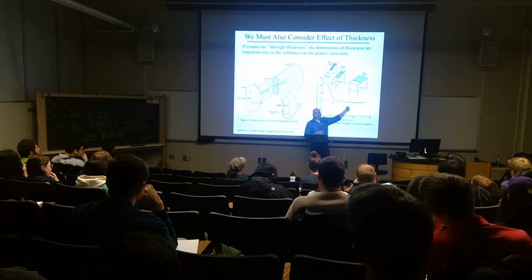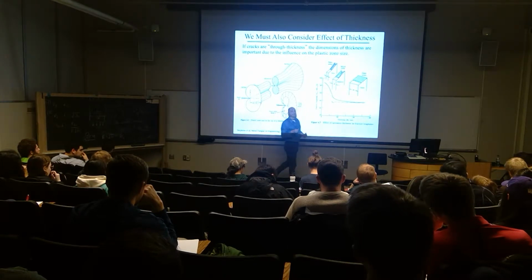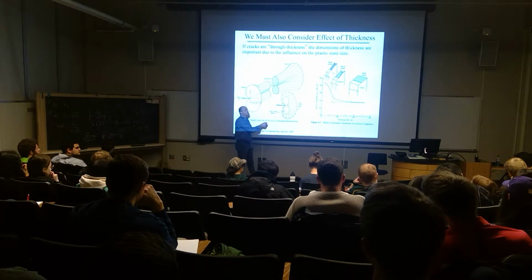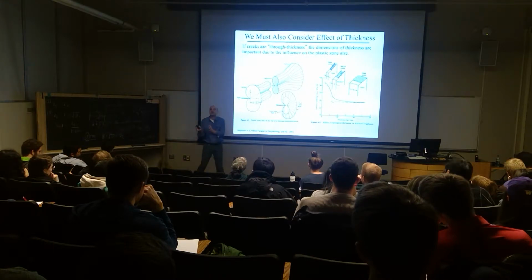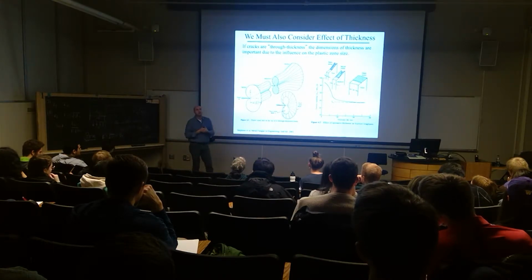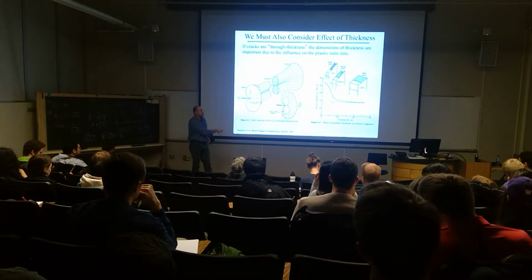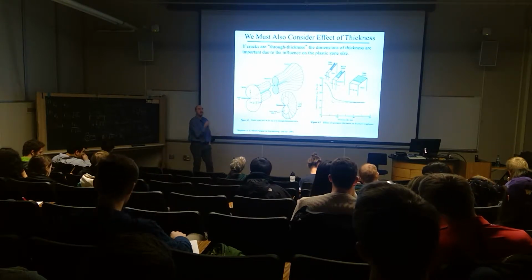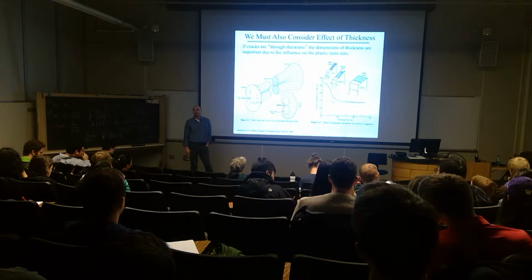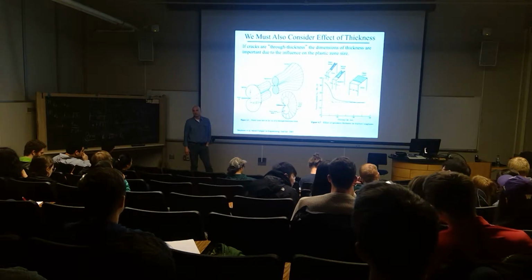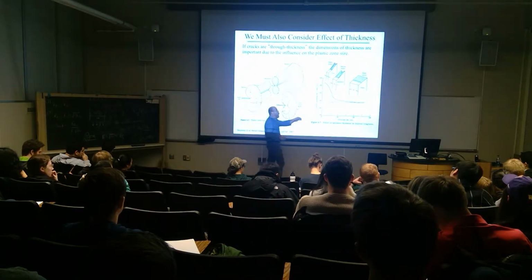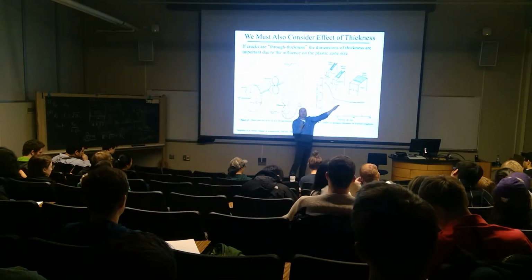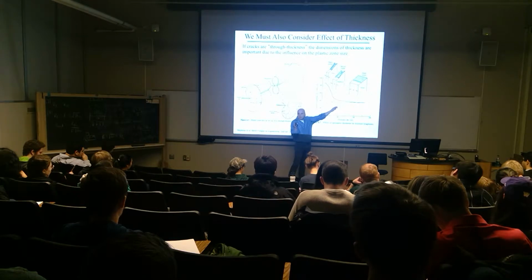So you need to be aware of whether your structure is thick or thin. You can have situations where someone increased the thickness of the structure to reduce the stress, but made that structure more likely to fail by fracture because it started to tend towards a plane strain condition of near crack stress. Okay.